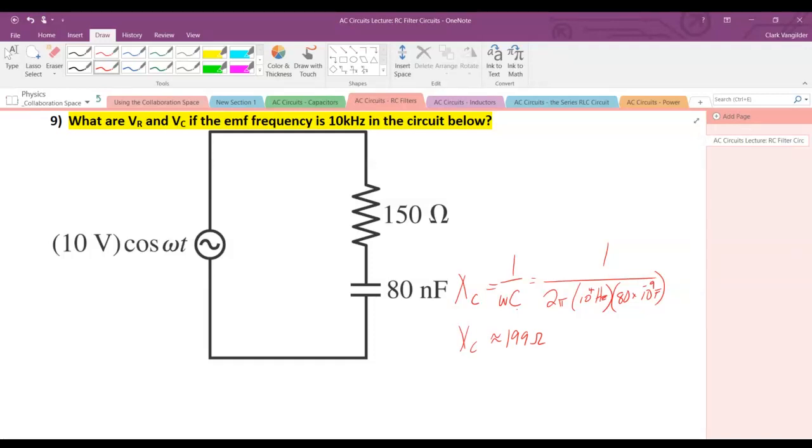And so that's that piece of the puzzle. And current, again, using Ohm's law, but it gets more complicated. Instead of it just being V equals IR, like we're used to in the old ways, it's going to be a little bit more complicated because we're not dealing with just R. In fact, we're doing two kinds of resistance, two kinds of impedance: the normal resistance that we have in a resistor and the reactance of a capacitor.